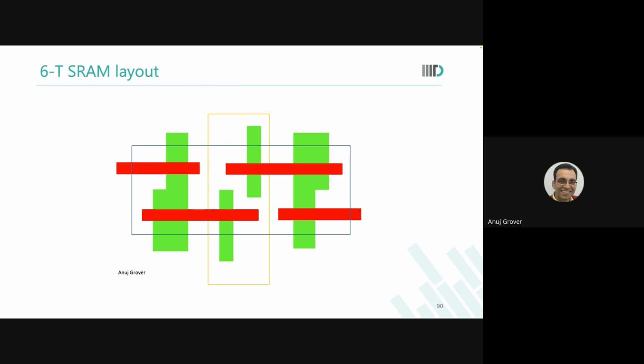Now, in the same memory cell, it can also happen that the pull down VT is a little larger. It can happen. It is probabilistically possible because they are independent devices. What does VT depend on? Dopants, oxide thickness. So some parameters might be related, but many other parameters are not related. We'll go into much more detail in mismatch and how this occurs in a later class. But at least this much we've already discussed in DVD. You have already run Monte Carlo on power, so what am I even telling you, who am I telling this to.